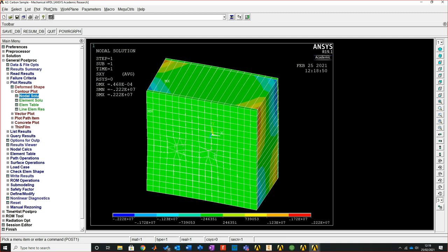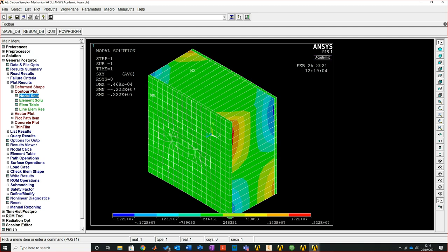And again, in this example, it is assumed to be a perfect relationship of the layups between them. If you know your material data to actually add into it, you can start to build true representations. If you know the relationship of something like a honeycomb aluminium structure, you can implement that into the relationship as well. So what you could have is, I don't know, 5 layers above, honeycomb core, 5 layers beneath, and then start to simulate that. And that's when that big question started to come out of Josh when he was a student.